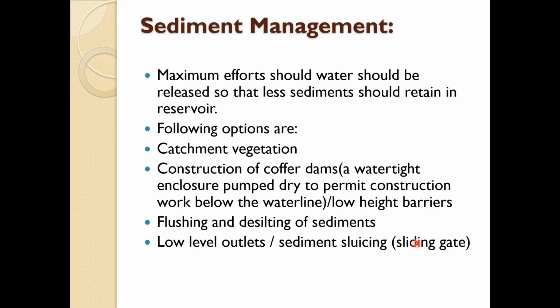Then the post construction measures. First is the removal of post flood water. The sediment content increases just after the floods. Therefore, an attempt is generally made not to collect this water. Hence, efforts should be made to remove the water entering the reservoir at this time.